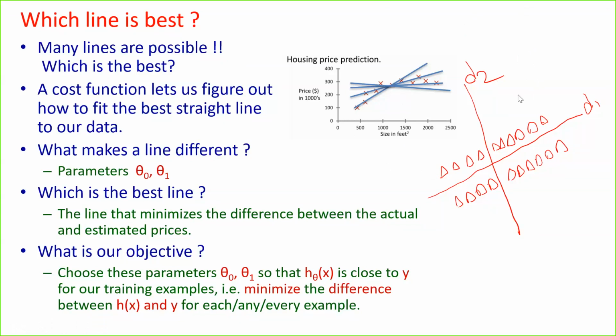They are aligned. D1. Why is it so? It is closer to all the houses. It is closer to most of the houses. Okay, it means that if I lay a common pipeline in this direction D1, then the cost will reduce. Am I right? Because the distance between the common pipeline and the individual houses is less in the case of direction D1, whereas the distance between the common pipeline and the individual houses is more in the case of D2.